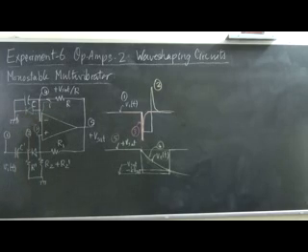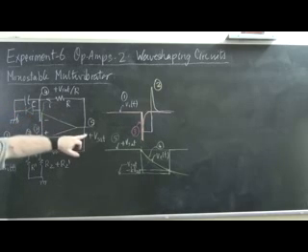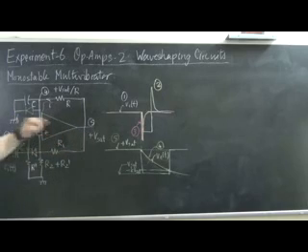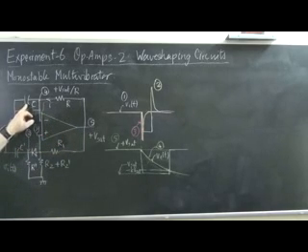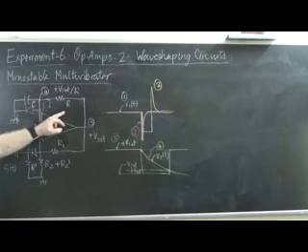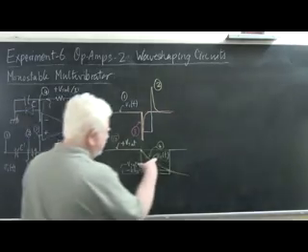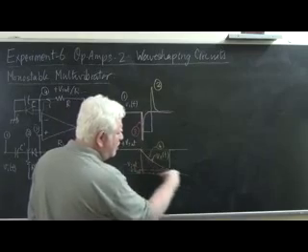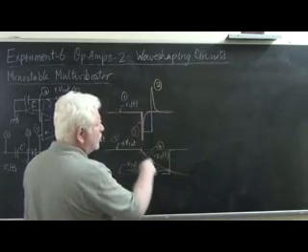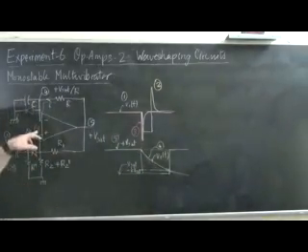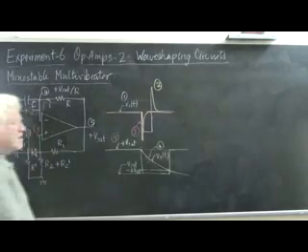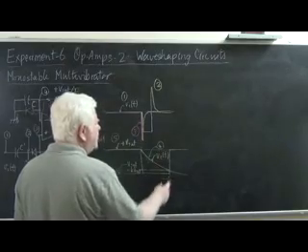This reversed diode is now open, and therefore this minus Vsat is the voltage to which this capacitor will aspire to charge through R. So this RC circuit charges downwards as shown in waveform 4 over here towards minus Vsat. It crosses the non-inverting terminal voltage of minus k Vsat at a certain point of time,